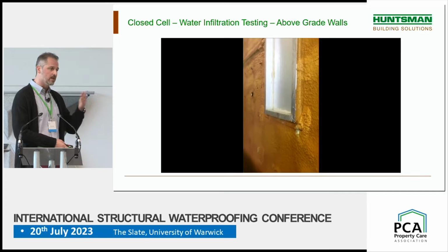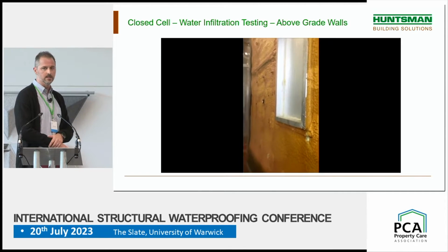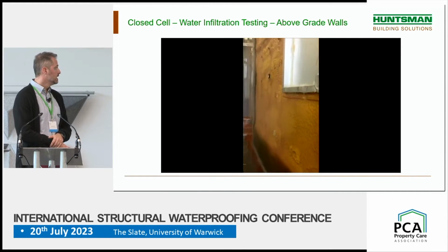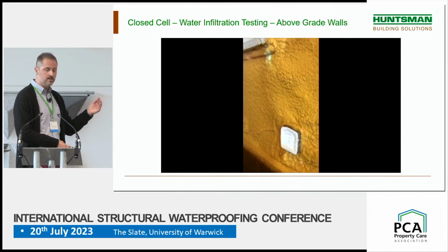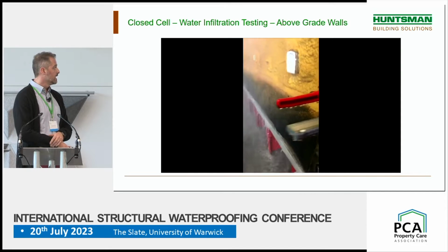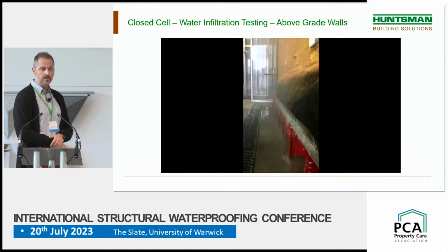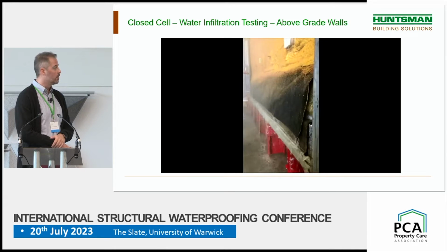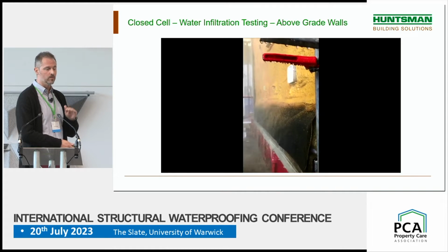And once you have a cladding installed, you'll never get these conditions on site. So after 15 minutes, there was no leak at all behind the wall assembly. That means that spray foam successfully passed the water infiltration test for above grade wall assemblies.